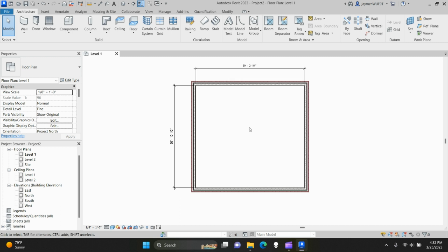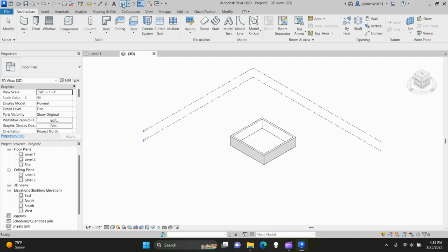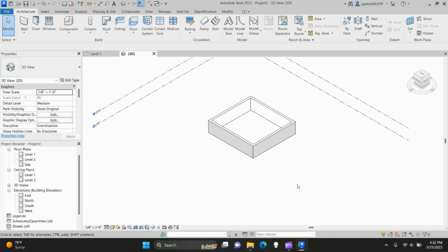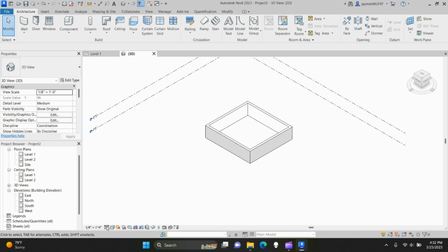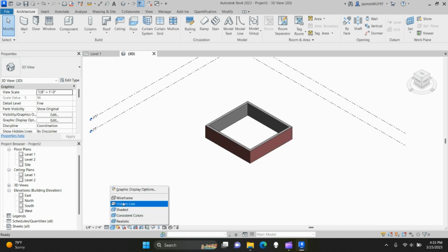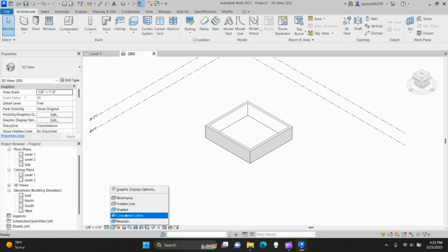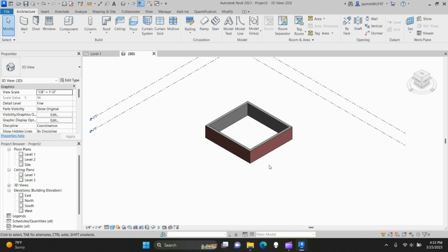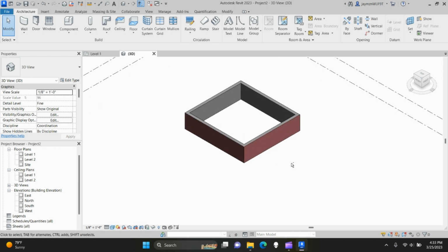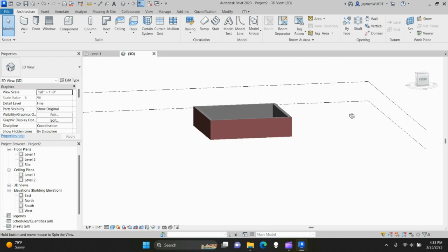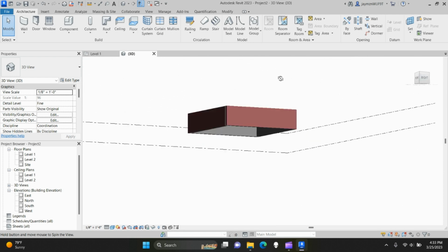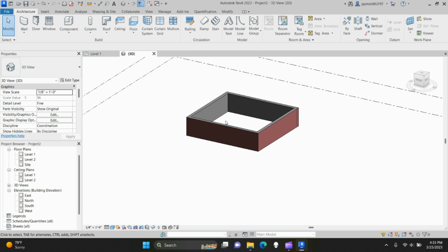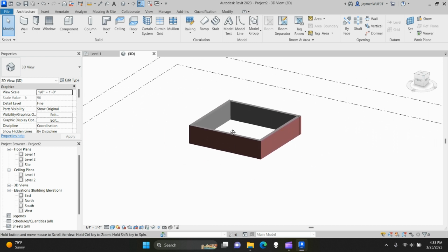And then when you're in 3D view, we'll go to that real quick. Your little house up top here, that's your 3D view. As you can see, it's set to the basics again. I'm going to change it to fine and shaded because I want to see materials. You can also do hidden, and it's going to keep it black and gray, or black and white. I hold shift and right click, and I can spin around whatever way I want to. And same thing, scroll wheel, click it in to navigate that way.